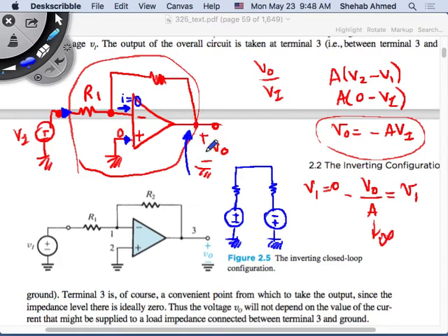Remember, this is an op amp. If the op amp is producing any output voltage, here we said that it has a value. Assuming the circuit operates, then the output has a value. This value is between this node and ground, and this value we decided is negative. It's a negative number, so I drew it this way. Then I have this voltage here, and a resistor in series with it. I'll call this R2, like they called it.